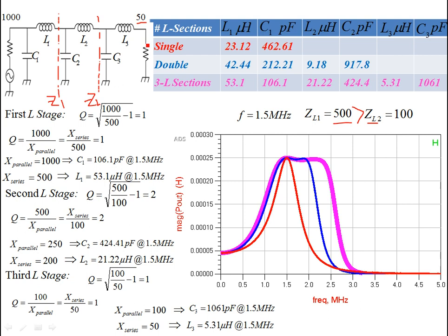Okay, so we have talked about this. This impedance is supposed to be greater than 50. This impedance is supposed to be greater than Z2. So Z1 is supposed to be greater than Z2, and 1000, that is your RS source resistor, is supposed to be greater than all of those. That's the story, and you continue this procedure if you want to cascade more sections.